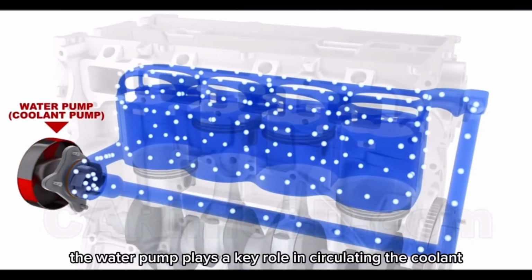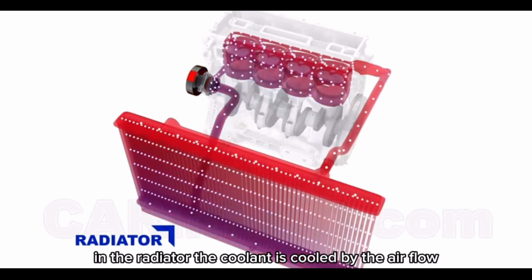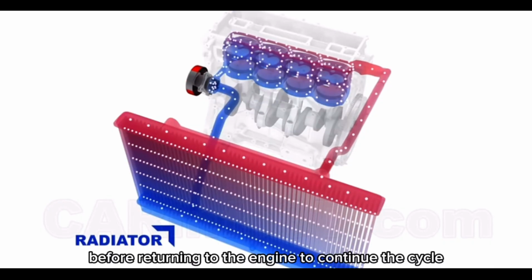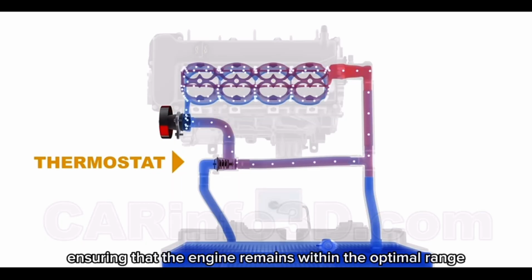The water pump plays a key role in circulating the coolant, which then flows into the radiator. In the radiator, the coolant is cooled by the airflow, reducing its temperature before returning to the engine to continue the cycle. A thermostat regulates the flow of coolant based on the engine's temperature, ensuring that the engine remains within